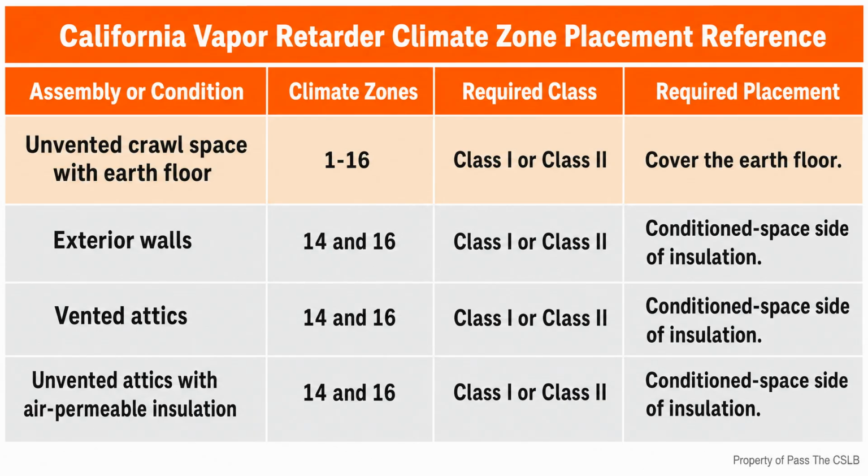Continuous insulation does not merely mean that bats touch each other from bay to bay. The framing still interrupts those bats. Picture a winter jacket laid over the entire frame instead of separate patches placed only between ribs. The jacket idea is the memory aid. The exact material, thickness, attachment, fire protection, and water management still have to follow the approved assembly.